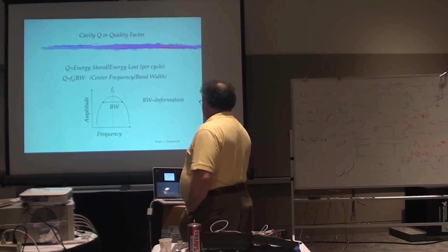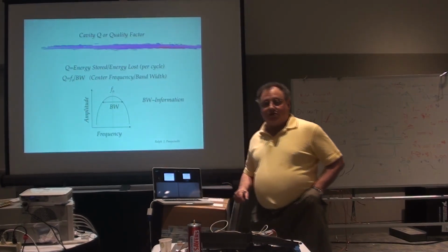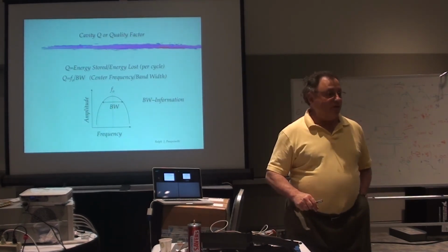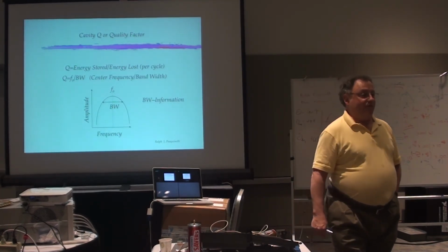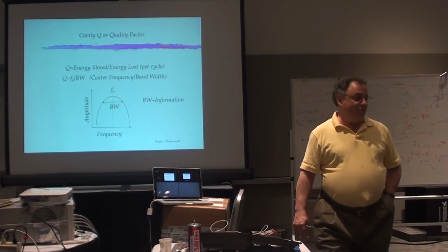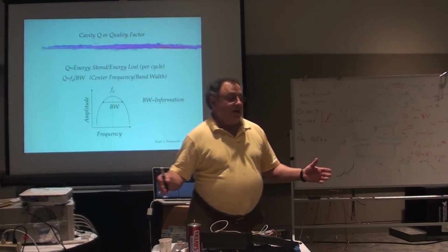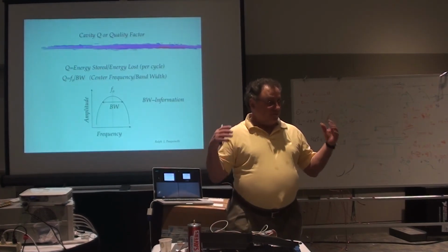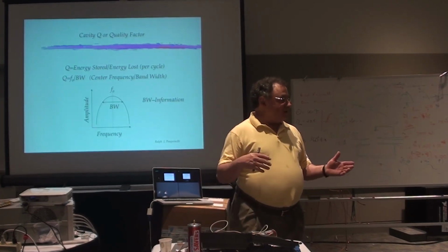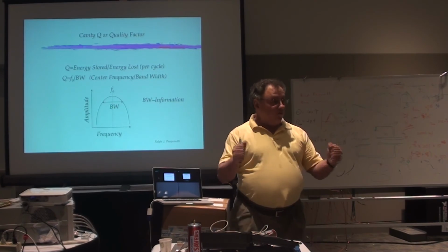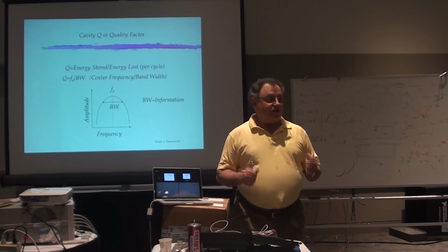Okay, and bandwidth is information. If your system is not an RF system, but maybe it's a damper, the damper is going to have a need for a much higher bandwidth. That says your kicker device is not a very high Q. And the only way that you're going to generate a lot of voltage in a lower Q device, because the shunt impedance is lower, is more oomph. And the power is very expensive.